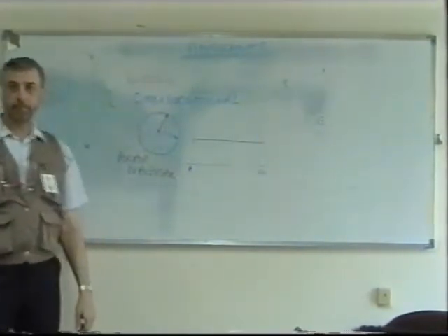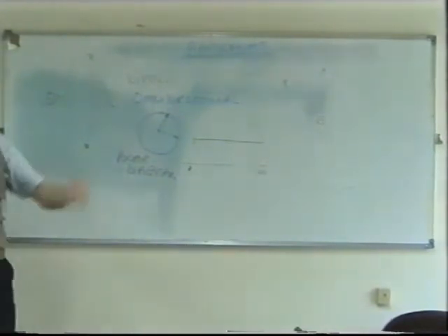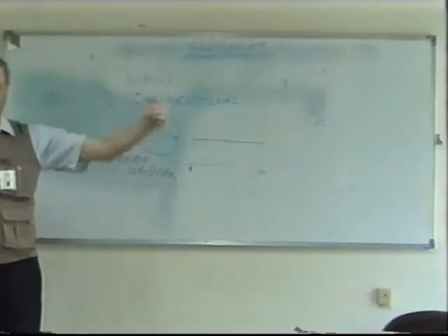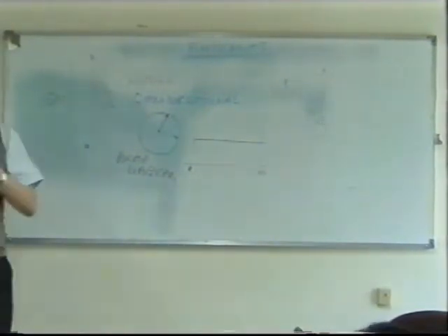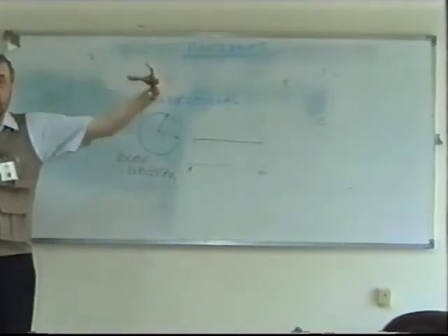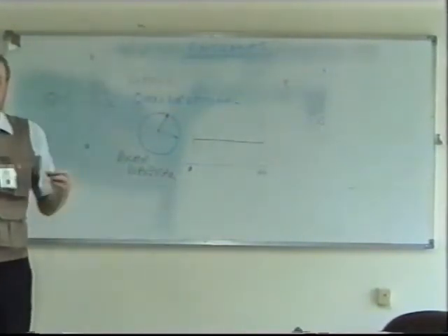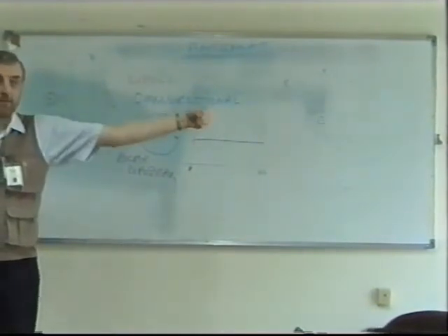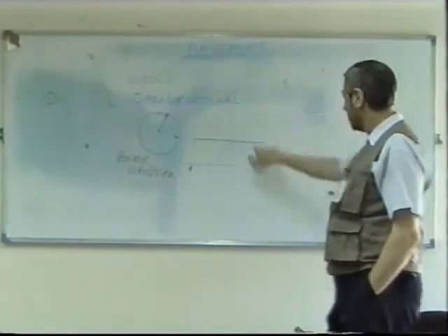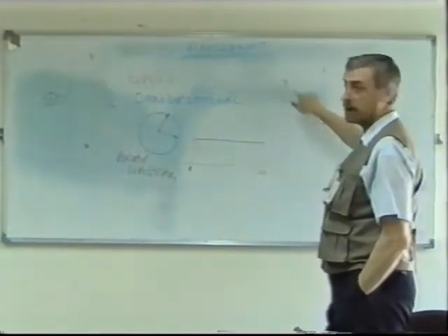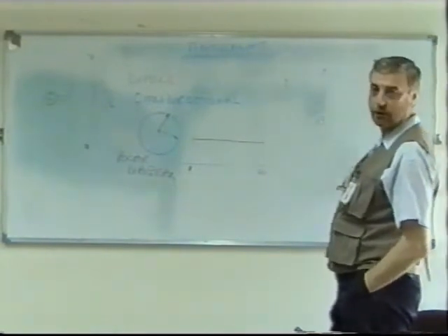But here it is written the strength of the field inversely with the distance. It does. As you get further and further away, the signal strength gets less and less, because you've only got so much power and it's radiating like a balloon, so obviously to fill that area it's got to get weaker and weaker, isn't it? That's the reason why in this example I said the car that travels around the antenna must stay the same distance, so that we make the same comparison at all points.